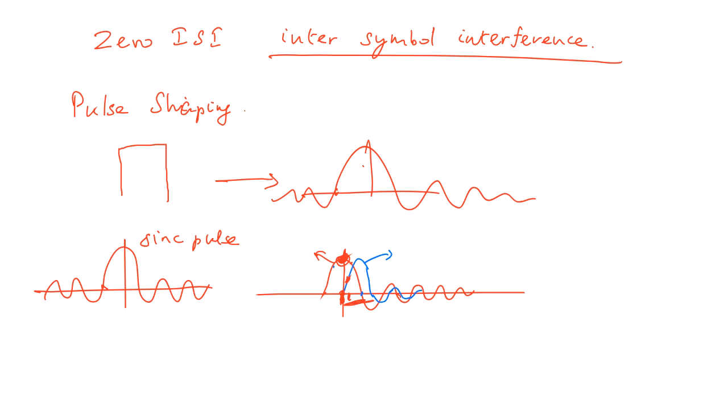It's ideal, but we do design systems which synchronize. That's why we have other mechanisms which avoid or minimize this inter-symbol interference. Obviously, it will not be zero, but it will be as minimal as possible, just like we can't have zero error probability, but we use techniques which minimize it to be so small that we don't face any problems. To make it exactly zero, our synchronization would have to be exactly perfect. Obviously, we can't do 100% perfect synchronization, so we achieve as little ISI as possible.